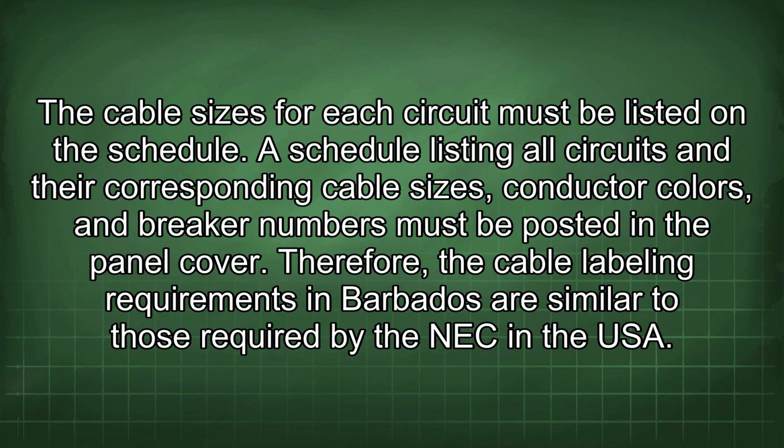A schedule listing all circuits and their corresponding cable sizes, conductor colors, and breaker numbers must be posted in the panel cover. Therefore, the cable labeling requirements in Barbados are similar to those required by the NEC in the USA.